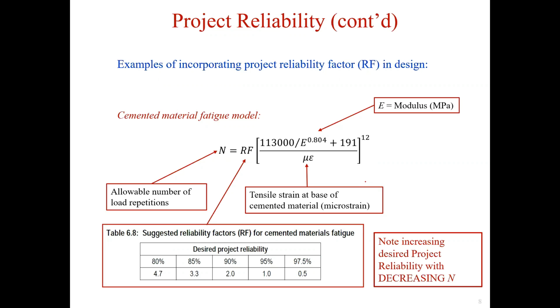We are having a design process allowing for the variability in performance between projects. So not all projects will perform the same. So we need to allow for that variability in our predictions of how long pavements will last. And we do that through the inclusion of reliability factors.